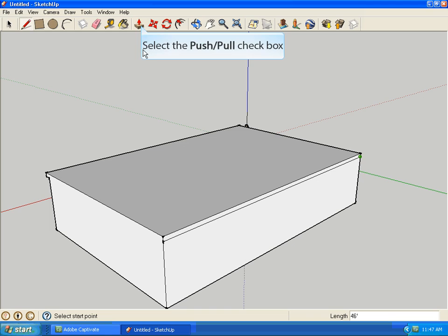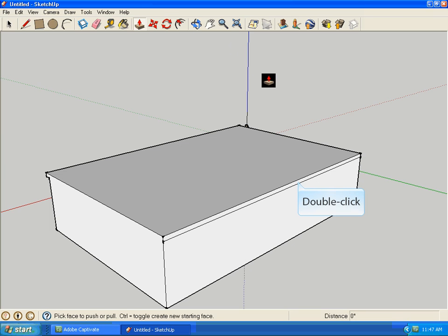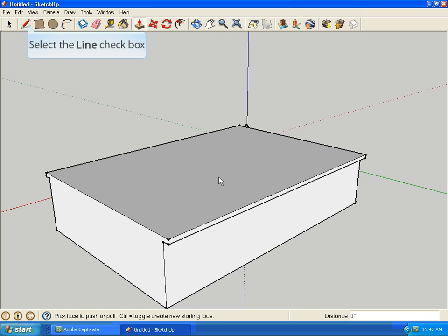SketchUp remembers measurements and is assuming that you would like to draw a line parallel to the one you made on the front side of the house. This is a correct assumption, so click on the red dot. Click on it once again and draw a red line across the rear face of the prism until it reaches the opposite edge. Once again, a red dot appears along with a flyout saying On Edge. Click on that dot. As before, click on the push-pull icon in the toolbox and draw the cursor down to within the newly drawn eave. Click twice. Again, SketchUp has remembered a previous command and automatically extrudes the eave 12 inches.